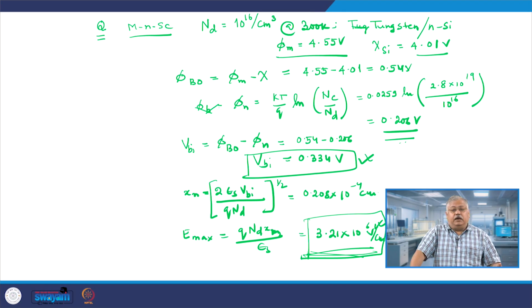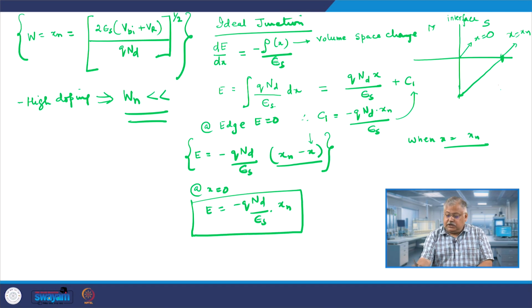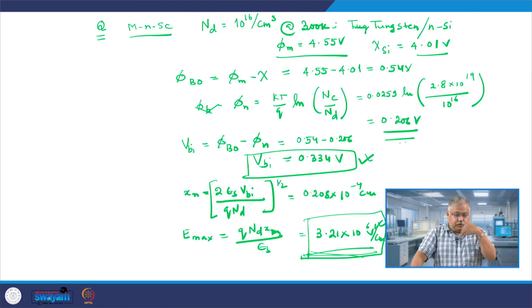And this electric field is negative in nature within the semiconductor, because we have seen it in the previous slide that this is negative in nature. It cannot be positive. Negative, why? Because it is just in the opposite direction of the voltage which you apply, and that is the reason it is negative in nature, right. Now, this was the ideal junction. Ideal junction primarily means the junction is perfectly clean with no impurities added to it, and there are no issues available there.